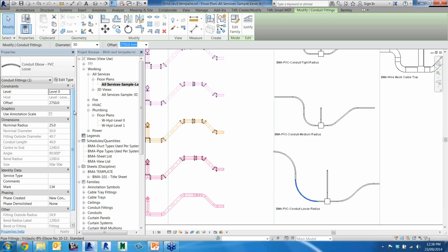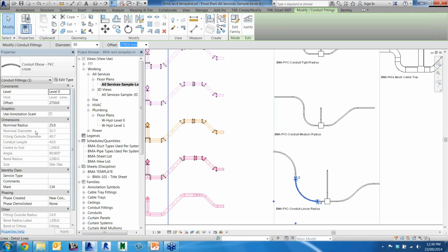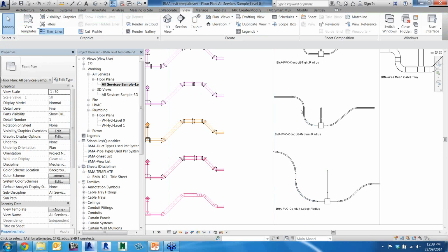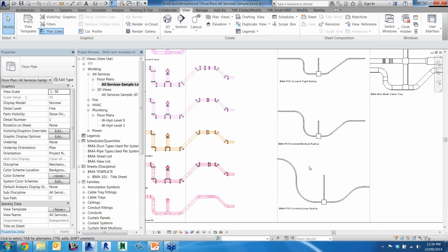We do also have, similar to the other elements here, with the conduits to some degree some radius override parameters in there, but generally these conduits are being controlled by the formulas within the family and also lookup tables, which you may be familiar with if you're working with pipes and pipe types and conduits, where these lookup tables in Revit are utilised. So yeah, those conduits are generally being controlled by those lookup tables.